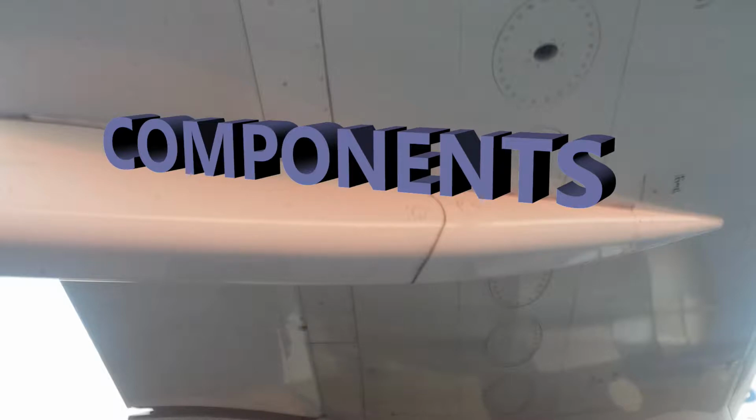That's what they're there for. So the fuses are used there to prevent the short circuits between your quantity indicating system, the cables there, and your electrical supply. So that's just all decreasing that risk of any kind of problem with too much heat, which can lead to some other problems. So temperature too high in that area.